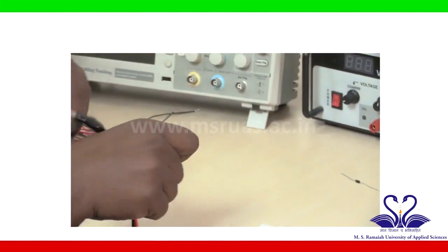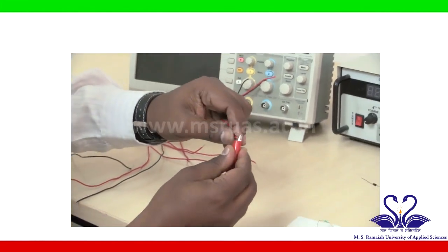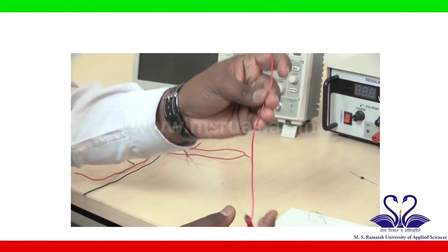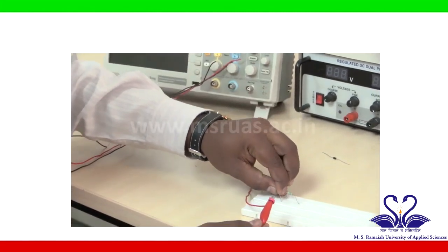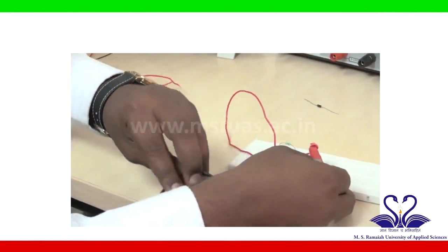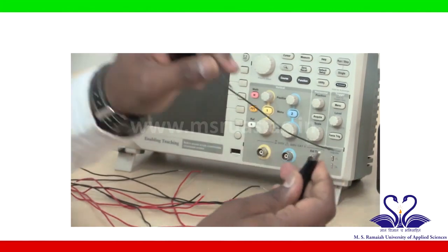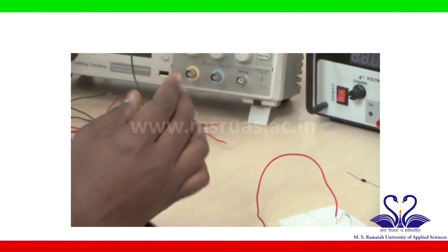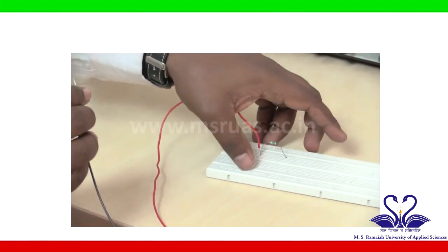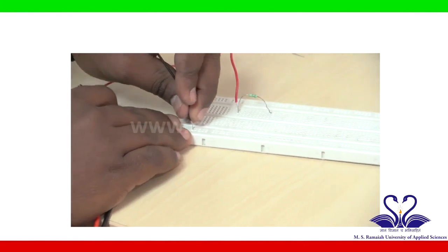Take one wire. I will connect to a positive terminal of a probe which is connected to the resistor one end, and the negative terminal of the input voltage is connected to the ground. So, this is the negative terminal of input voltage. Let us take the bottom first row of a breadboard as a ground. I will connect to a ground.